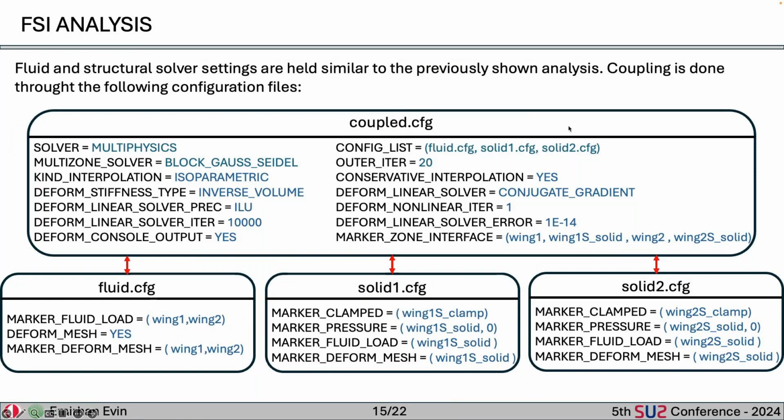Also, there's an important factor: you need to define the marker pressure and give it a 0 Pascal load. You also need to define the marker fluid load. If you don't do this, it cannot solve properly.